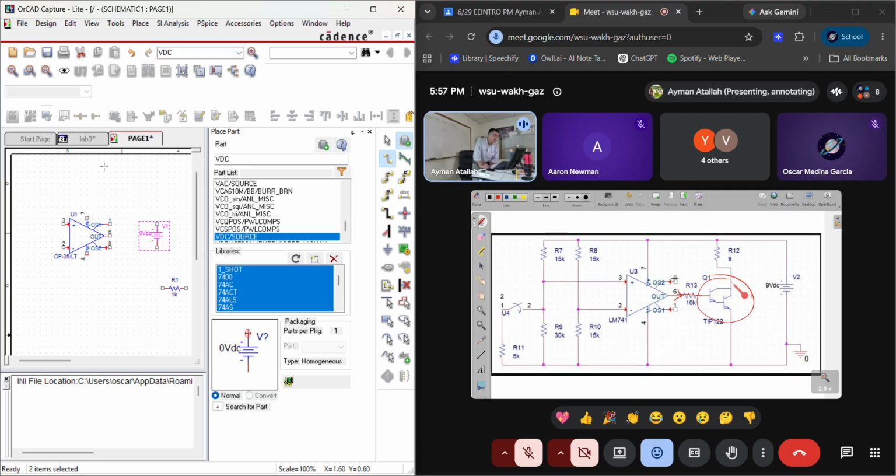This is a special kind of transistor. We studied this before. It's called a Darlington pair. It's like two transistors together, usually power transistors. Because of the very high amplification of this transistor, it needs very little current. That's why I connect 10K here, because I don't need much. A little current from here is enough. So when the output voltage here is high, it will give enough current here, close this switch, and current will pass.